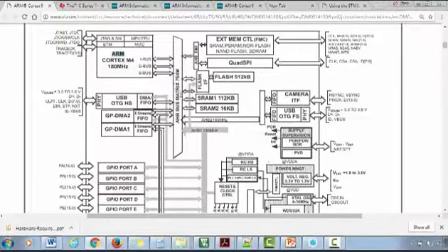So the bus matrix is your traffic controller kind of guy who decides which bus to connect at a given point in time. That means the bus matrix will actually serialize the access. So the answer for this question is: GPIO connects to the ARM processor over the AHB1 bus via the system bus.